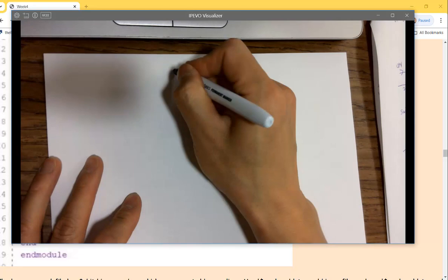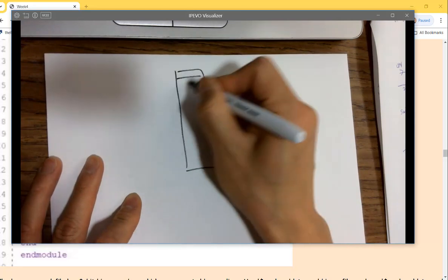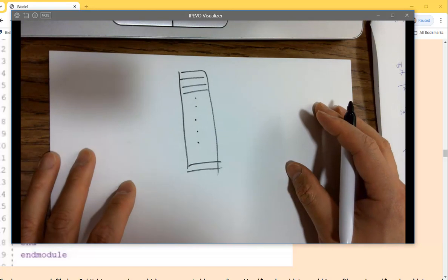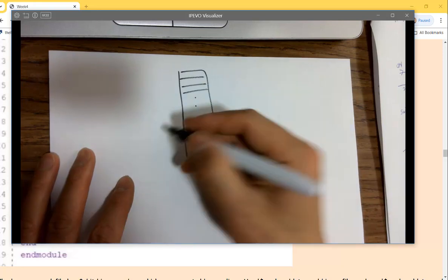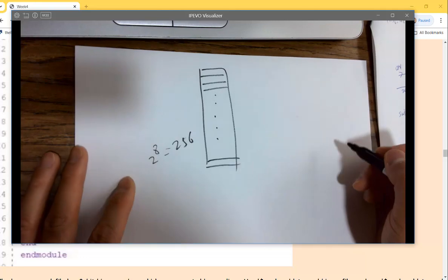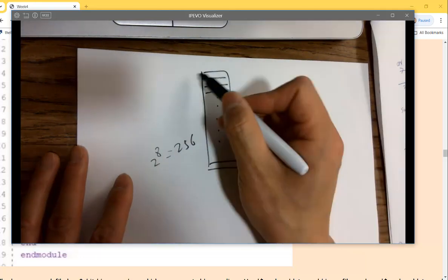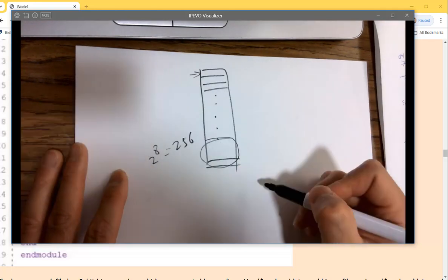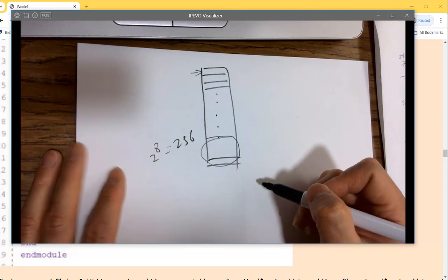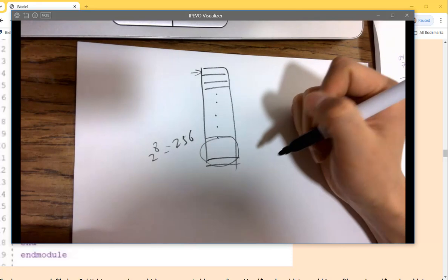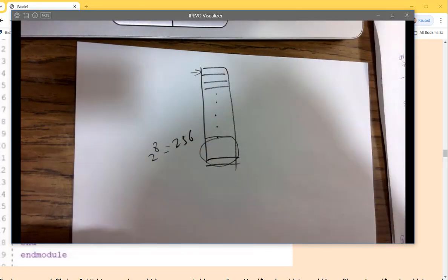So the memory bank has 256 lines, and so you need 8 bits to enter every address, right? If you have 7 bits, part of the memory banks are not going to be accessible at all. You throw a number in there, but you'll never be able to get them. So can you use 9 bits? Yeah, you can use 9 bits.